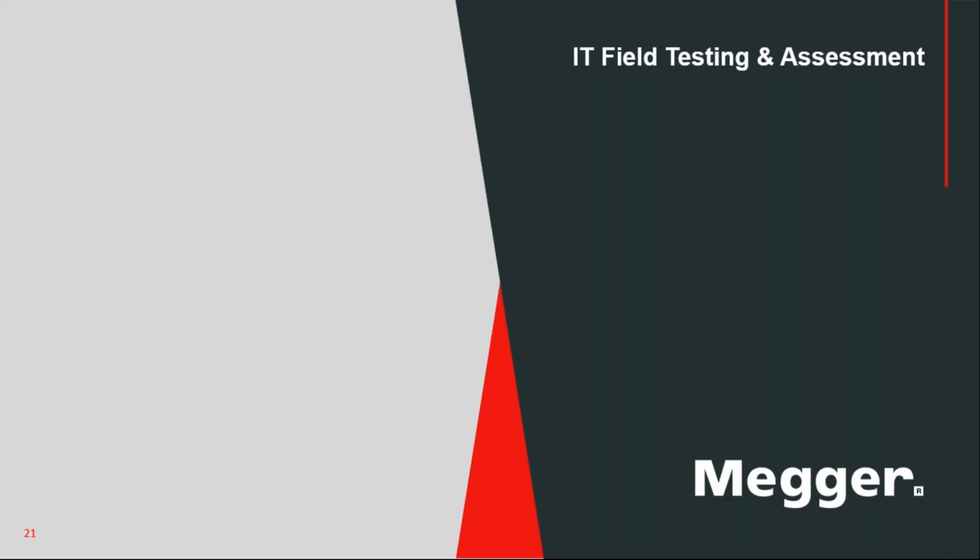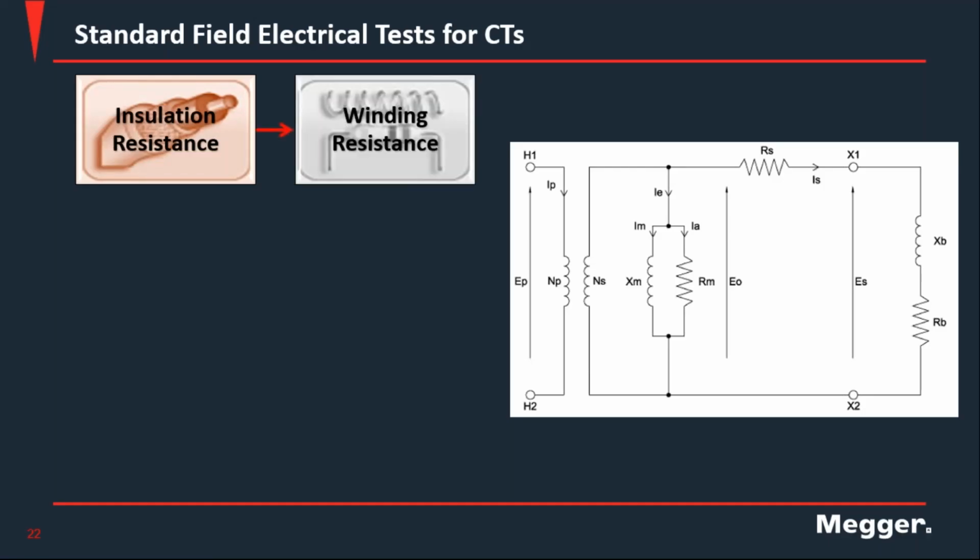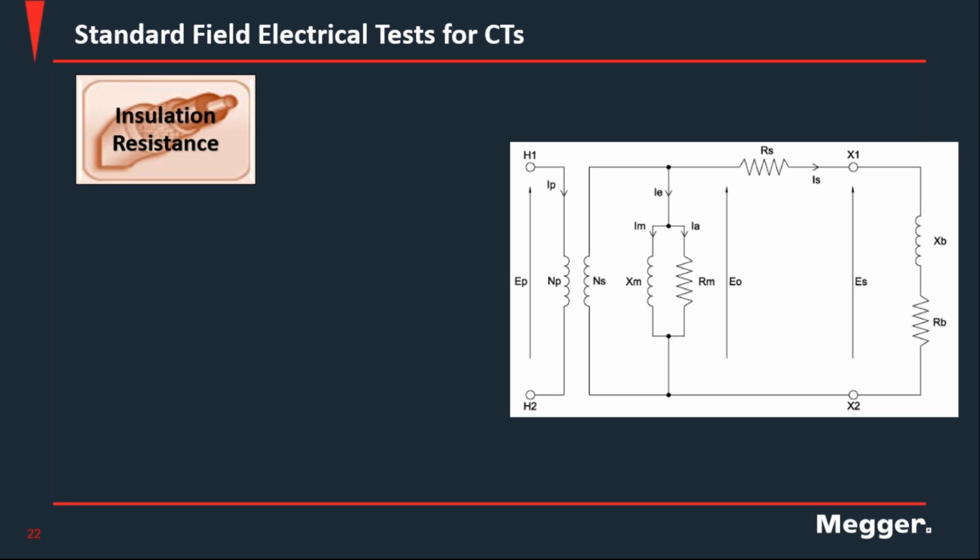Let's look into the results. Let's talk about the different test activities that you perform. So of course, for any electrical equipment, the very first test you want to run is insulation. And you want to assess the insulation. And in this particular case, I'm showing insulation resistance.